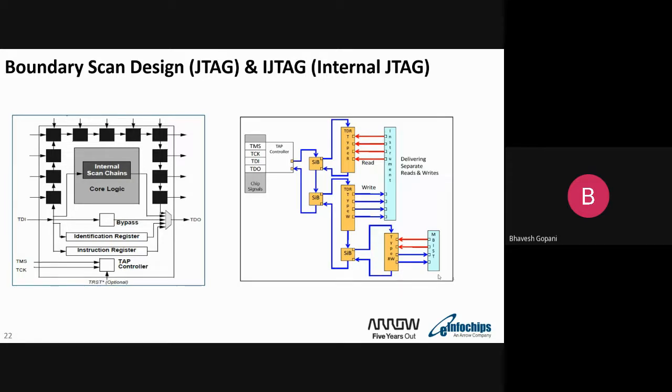There are certain blocks inside the PLL, as we know, like the VCO, low pass filter, and phase shifter. We are not worried about what is inside the PLL, but how many inputs we need to provide. There are 120 or 130 other inputs. Reset, then programming inputs, like how many bits I want, because for 1 gigahertz, how can I calculate it?